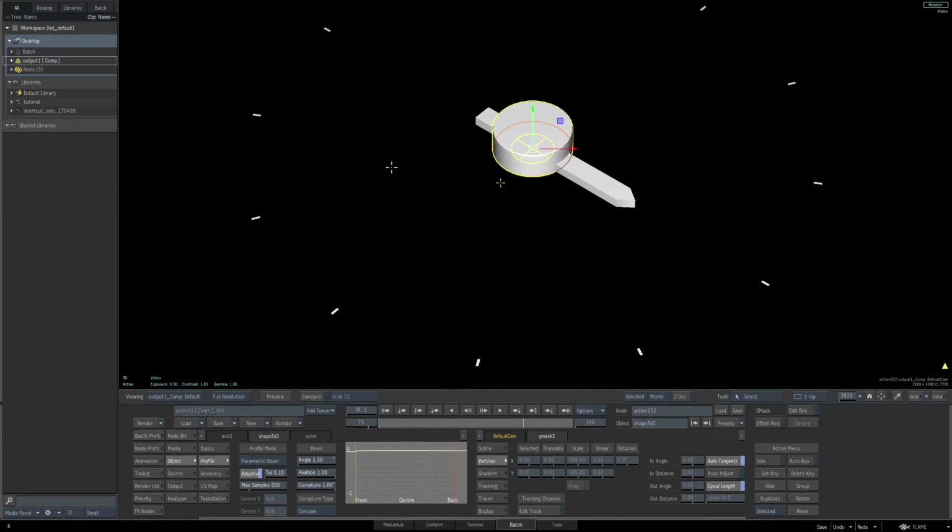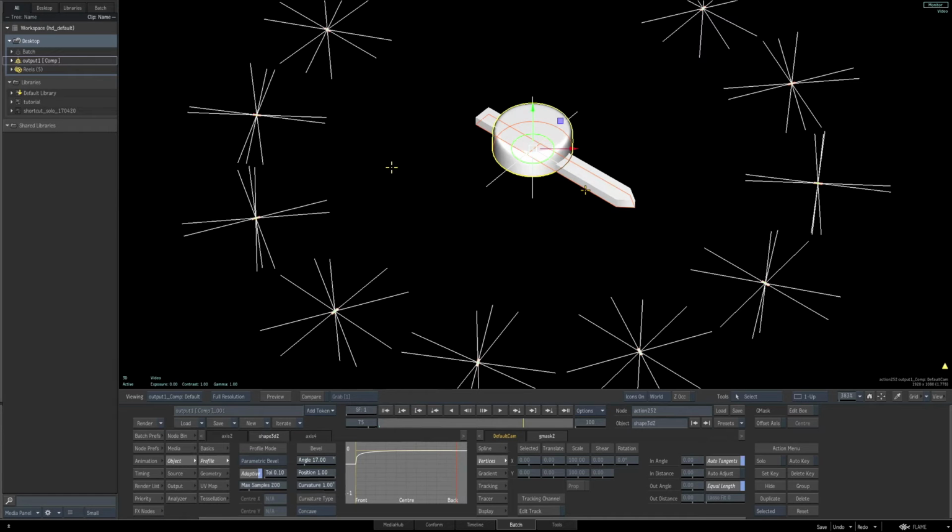You can see it updating in the viewport and also in the graph next to the parameters. And we can enter an exact value of 17. Now I'll hit I twice to show all icons once again. And then I'll select the long extended part of our dial. Once again, we'll adjust our curvature to 1 and then start to adjust the angle. Let's put a value of 18 for this angle bevel.